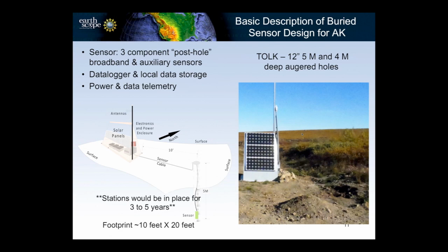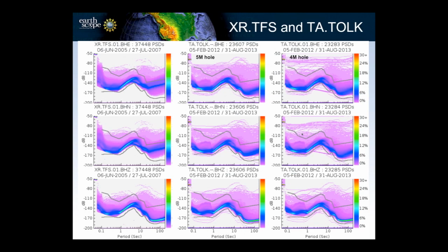And so we couldn't do the TA vault at every site in Alaska because we wouldn't have road access anyway. The standard TA vault would probably also have serious issues in areas with permafrost of tilting due to the freeze-thaw cycle in the shoulder seasons. And so this is a way to get your seismometer below that active layer. And as I'll show at Tolk, it's been quite successful.